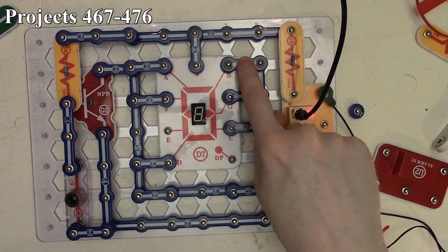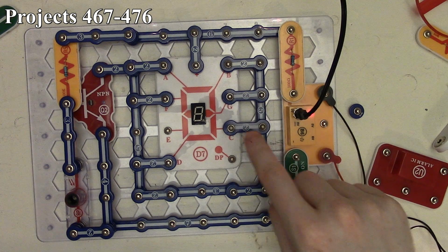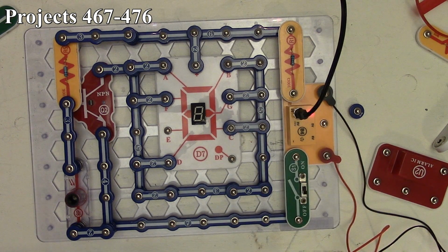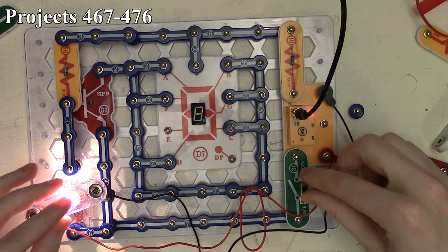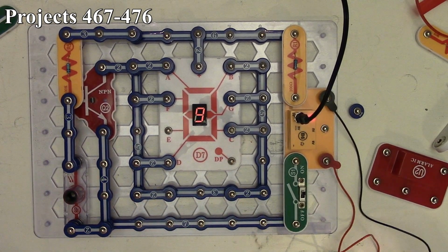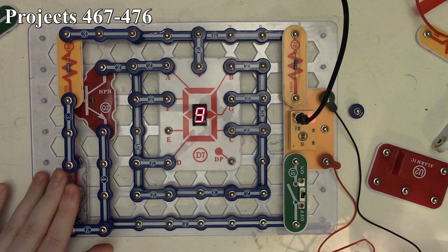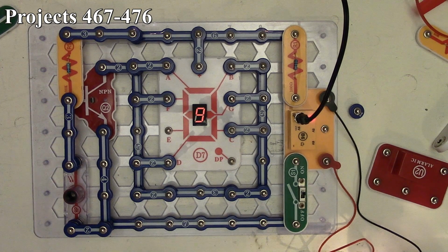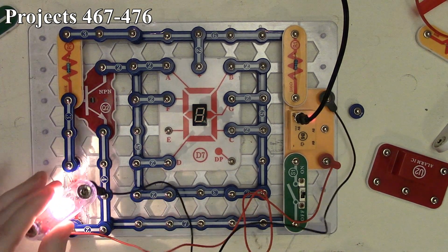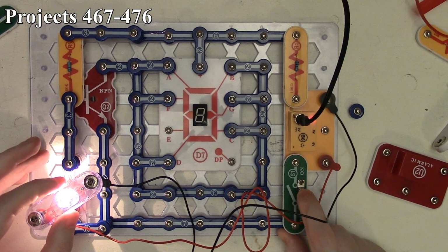A, B, D, F, G, and C. I don't know why they couldn't have gotten A, B, C, D, F, G, but whatever. So, bring our light over, turn on the circuit. Again, number 9 doesn't display, we take it away, starts to show up. Cover up our photoresistor, it gets nice and bright. Let some light in, starts getting dim. Bring our 6-volt lamp over, and it goes completely out.